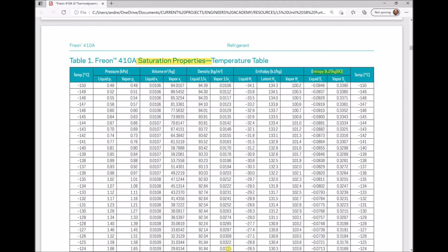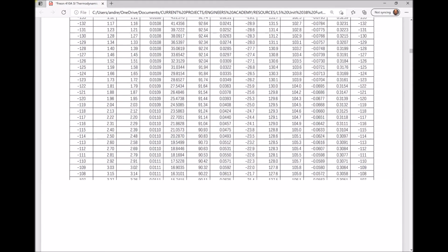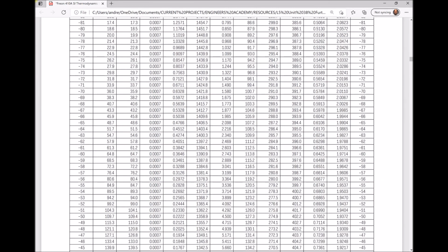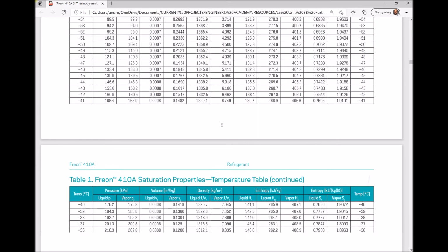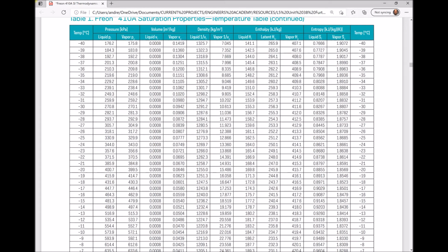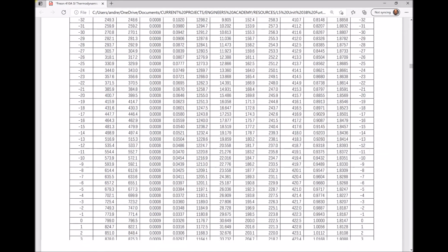Now, as we see here, we have a value SF and we have a value SG. Well, we also know that position 1 is on our dry saturated vapour curve, so we're going to be referencing the SG column. Now we're going to track down that column until we find our desired entropy value of 1.8149, or somewhere close to that value. So here we're at 0.3, so these ones are no good. Here we're going through the 2s and the 1s, so we're getting closer to our value. So if we stop on this page here, we're looking for an entropy value of 1.8149.